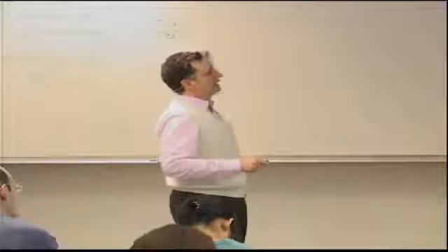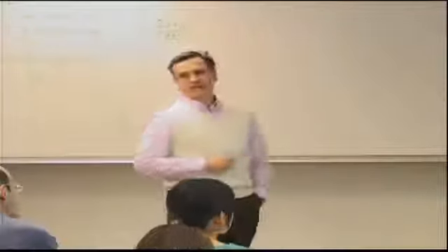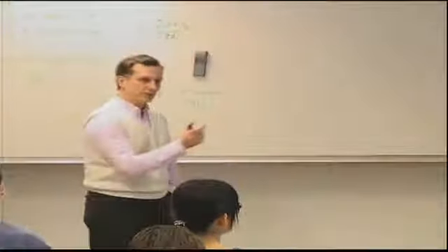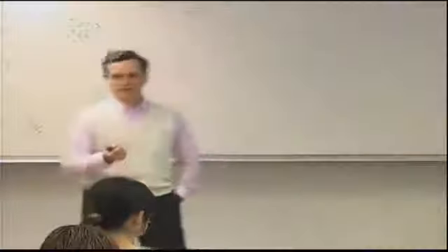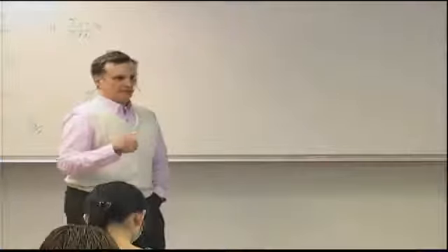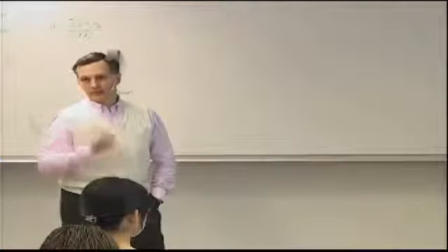Okay, so let's look now at this configuration. There's this stiffener, which is the stiffener we've been using all along throughout the course. And then there's a portion of the skin that is associated with that stiffener. And how much of that skin do we take? Remember when we talked about the effective width, we said it has something to do with its importance comes in also during the post-buckling.